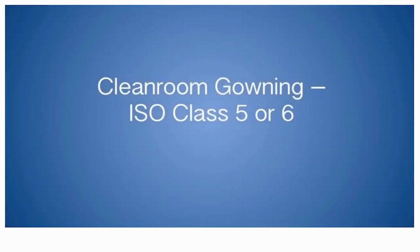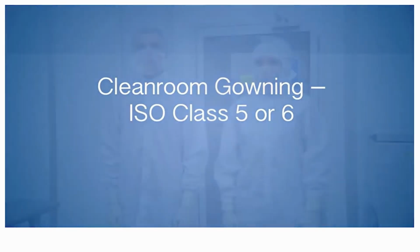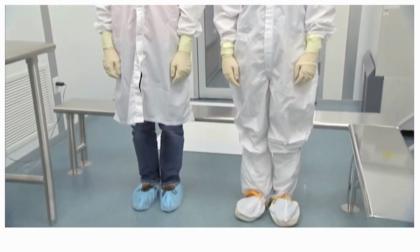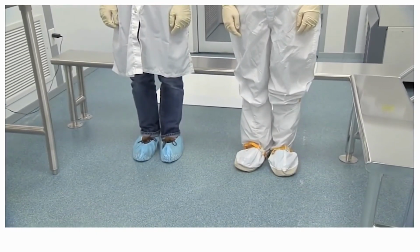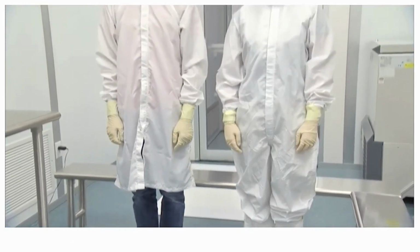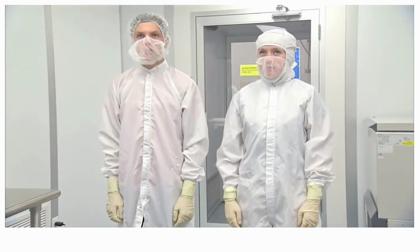Clean room gowning, ISO Class 5 or 6. Gowning for an ISO Class 5 or 6 clean room is slightly different than gowning up for an ISO Class 7 or 8 clean room. Instead of a smock, a full set of coveralls, or bunny suit, must be worn. However, the same principle as before follows, and the gowning process should go from the top down, starting at the head.